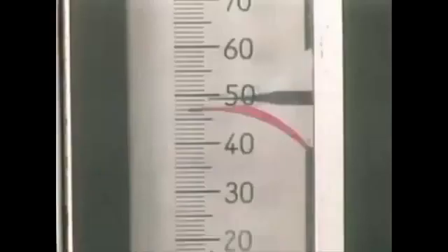A distillation system functions most efficiently when its feed rate is kept within an established range. When the feed rate is regulated by a flow controller, slight variations in the rate can be expected. However, large variations can greatly affect a column's performance. If a system's feed rate is too high, overloading can occur. Overloading is a condition in which the vapor rising up a column is impeded by the liquid flowing down the column.